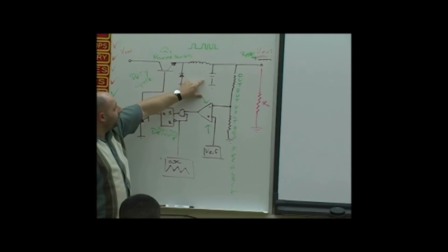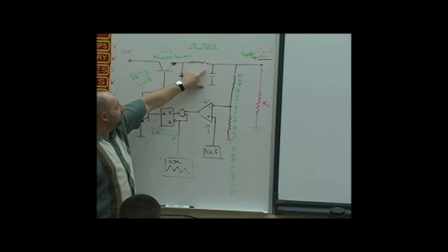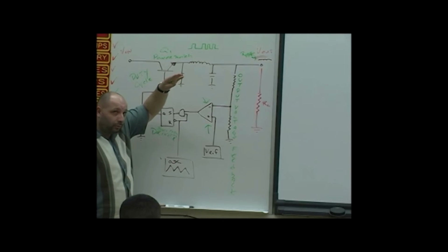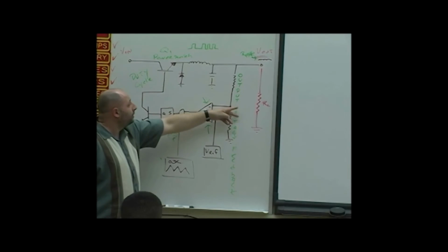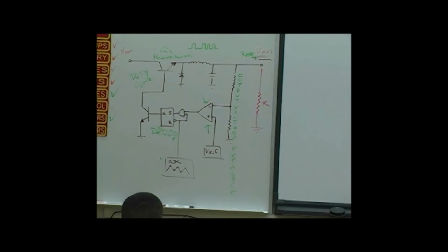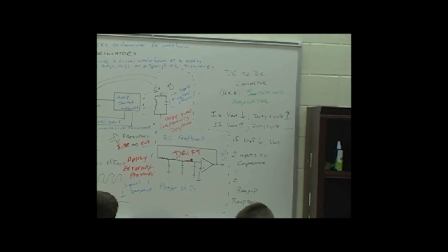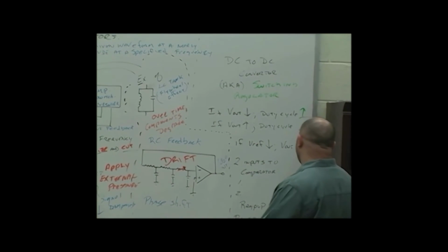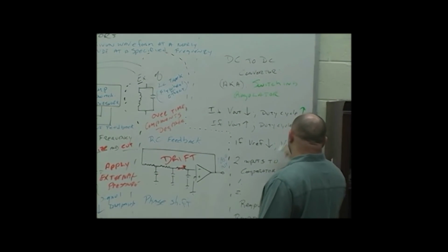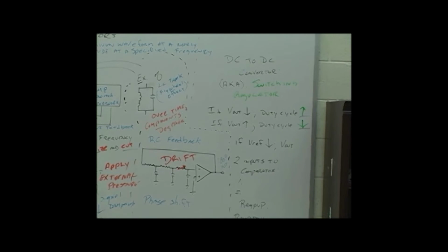So it really boils down to this. Whatever this capacitor level does, rises or lowers, it's going to reflect what the output voltage is going to be. So we're just trying to sustain the level of output due to change in load. If my output is above the level, what does the duty cycle transistor have to do? Decrease. Yeah, it's got to chill out a little bit. So ultimately, the level of output and the duty cycle are inverse to each other.